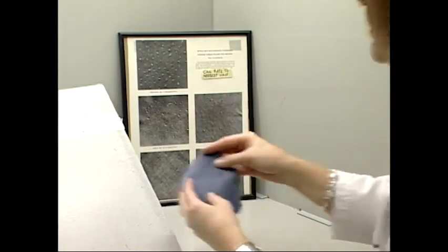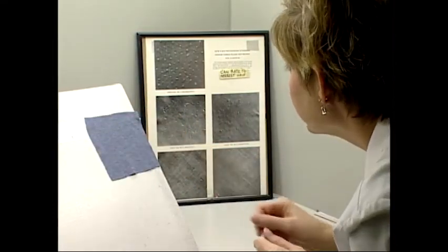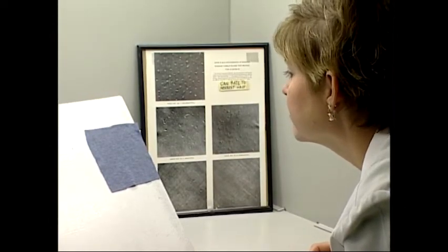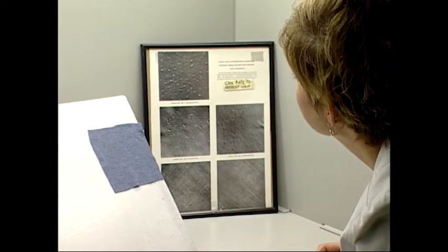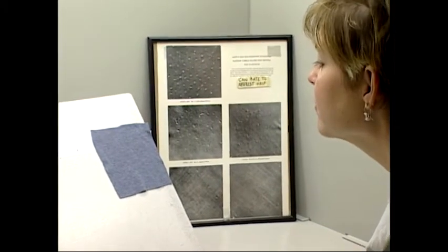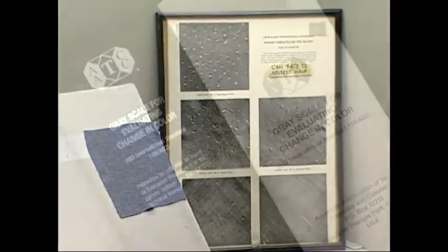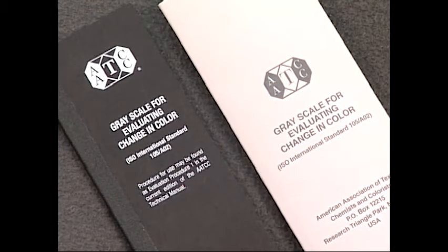Standardized rating scales are used to compare the tested specimens to an approved series of replicas. In these instances, a sample of the standard, a specimen that has not been tested, and a specimen that has been tested are compared. Finally, the rater assigns a rating number for the difference between the tested and untested fabrics. Standard reference scales are used. The most commonly used rating system is the AATCC Evaluation Procedure 1 Gray Scale for color change. It's used to rate color change in textiles as a result of testing.